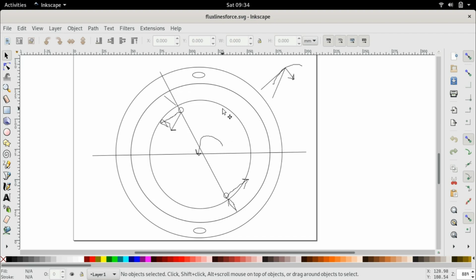But theoretically, it is next to impossible for us to actually take all these construction details into account and calculate the entire torque produced because of all these stator slots and all these rotor bars and actually sum them all up. Because we are looking at hundreds of slots and we are looking at probably, even if not hundreds of rotor bars, dozens of rotor bars. So just imagine the amount of calculation we have to do. It may not be possible to even just simply integrate it, because remember, these are discrete slots. These are not slots which are actually placed at infinitesimal points all over the circumference. So a simple integration may not also do. It might actually need a very, very complex form of calculation.